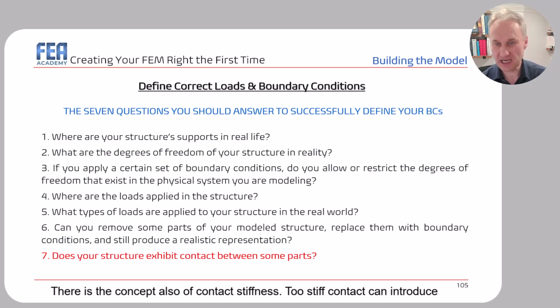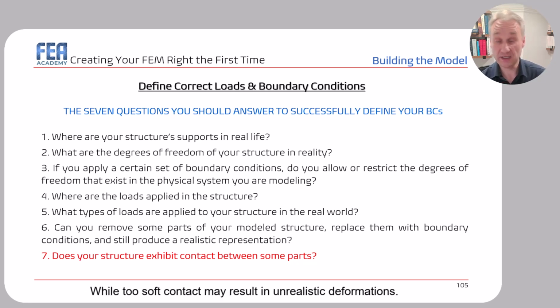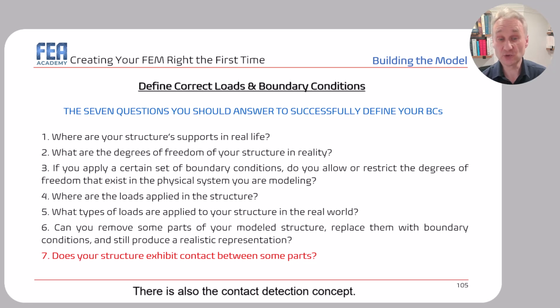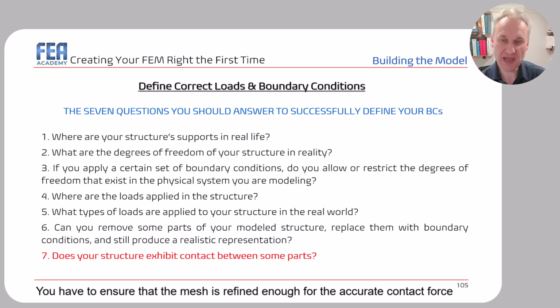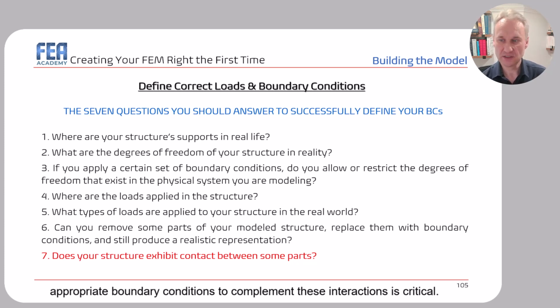Too stiff contacts can introduce artificial stress concentrations, while too soft contacts may result in unrealistic deformations. There is also the contact detection concept. You have to ensure that the mesh is refined enough for the accurate contact force distribution. If your structure has significant contact interactions, selecting appropriate boundary conditions to complement these interactions is critical.